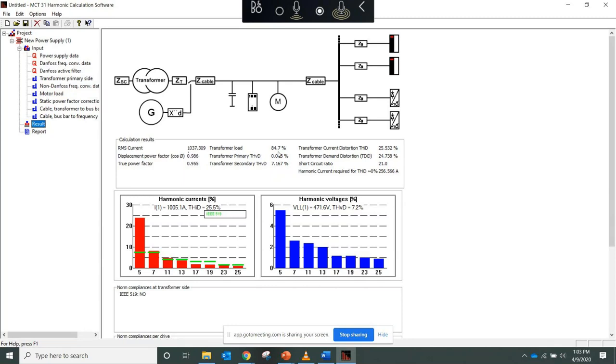This would depend on the process. Am I a remote lift station with nothing around me? Probably be okay, maybe. In the municipal water world, we live in the world of redundancy. So the odds that they're running all 4 of those at the same time at full load is absolute worst case scenario. Most likely they'll run 3 drives and the 4th drive will just be a spare, or they'll cycle it through in an alternation.